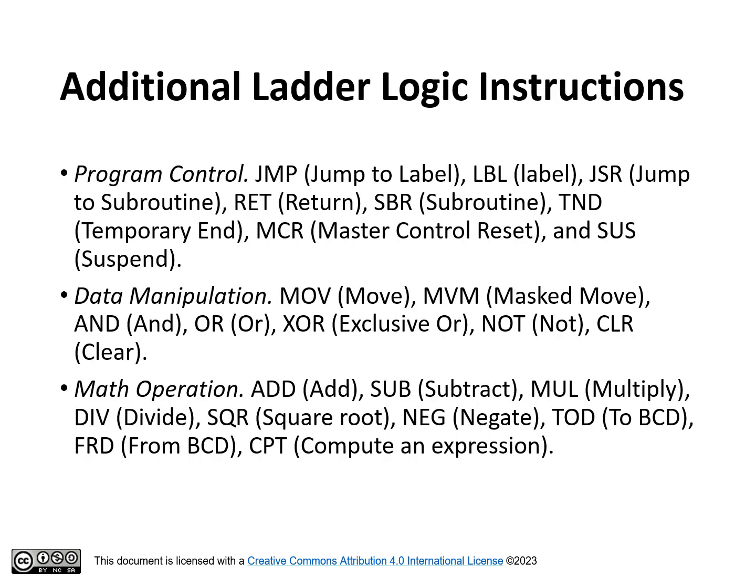The following list of other ladder logic instructions is grouped according to functionality. Program control: JMP for jump to label, LBL for label, JSR for jump to subroutine, RET for return, SBR for subroutine, TND for temporary end, MCR for master control reset, and SUS for suspend.